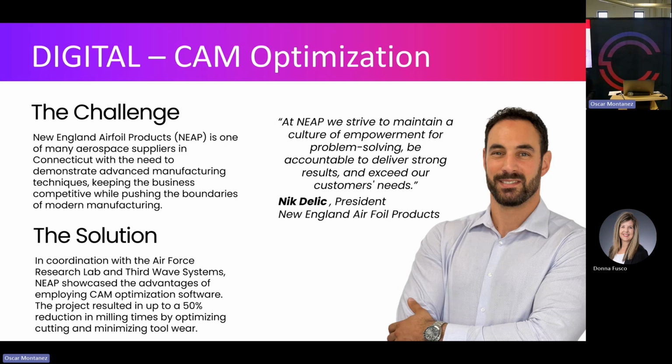We use PolyWorks, and we also have Geomagic here. Actually, we have a number of different inspection softwares. All of them can open up the QIF file. So if I'm receiving model-based definition, we also have PC-DMIS here with the Hexagon technology. We can open up that file, and it's literally a few mouse clicks. It's the same thing. You set up your strategies. Once your inspection software knows, for example, if we're doing CMM, how many points to take on a particular feature given the tolerance, it can automatically apply that strategy afterwards.